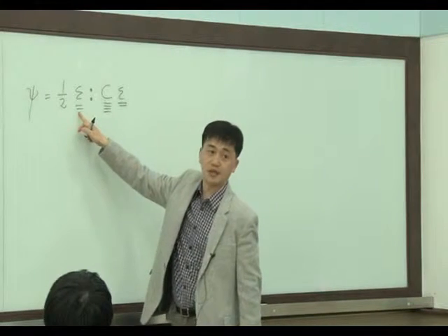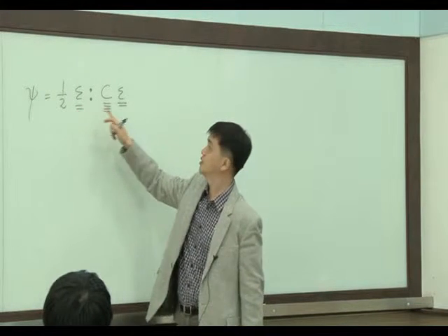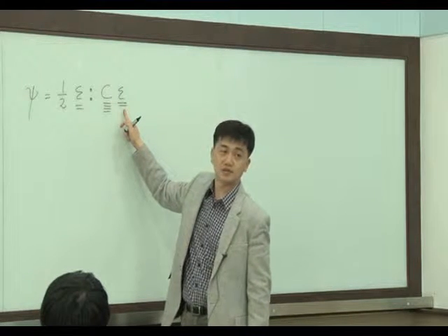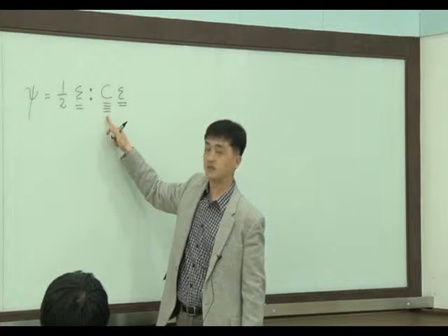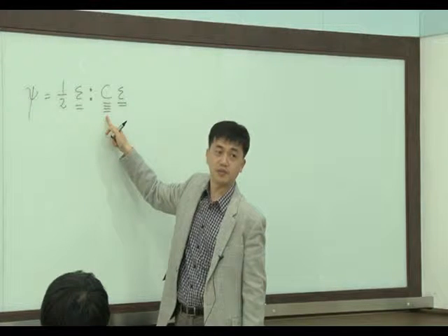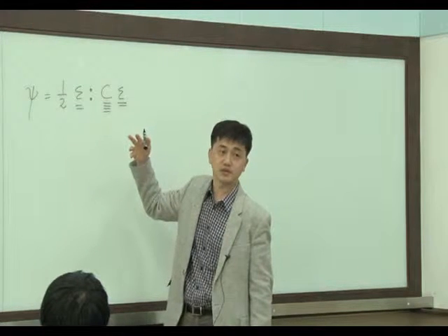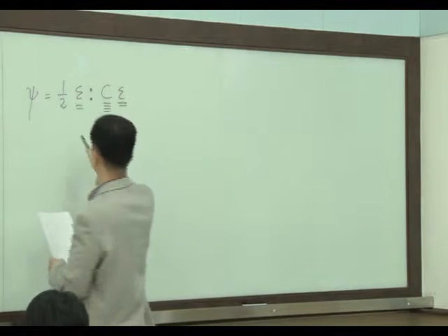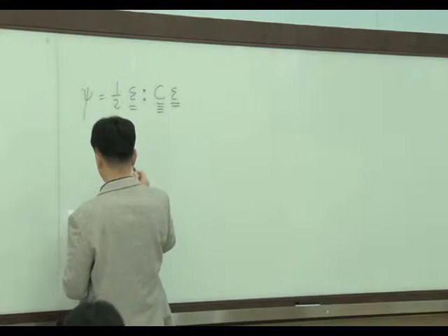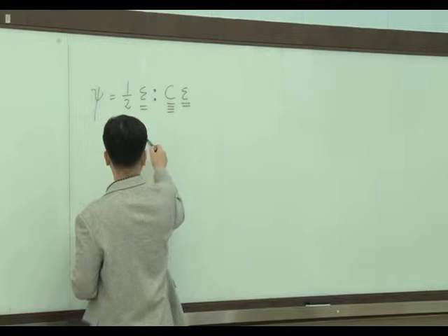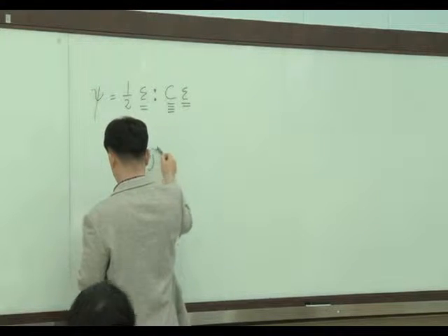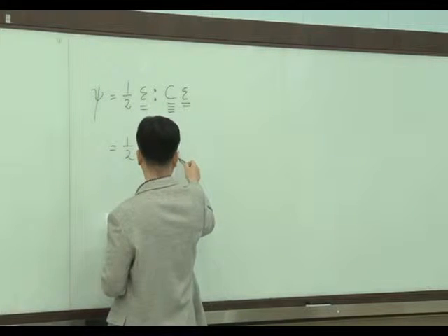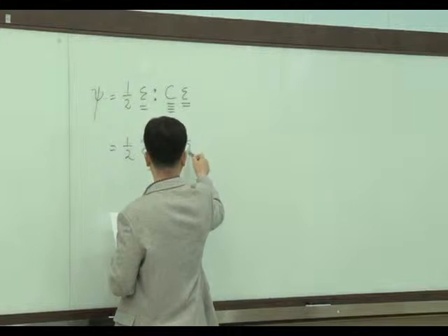This one has a 2 on the bar. This means it is a matrix or second order tensor, and strain is also a matrix, a second order tensor. This is a 4 on the bar. It means fourth order tensor. In tensor form, C ijkl epsilon kl.